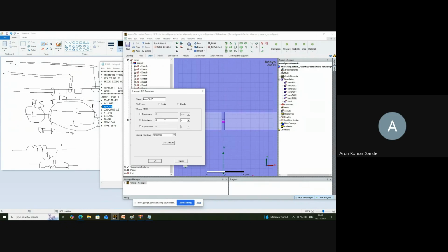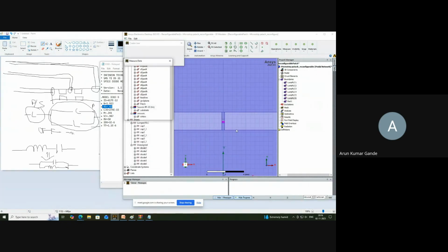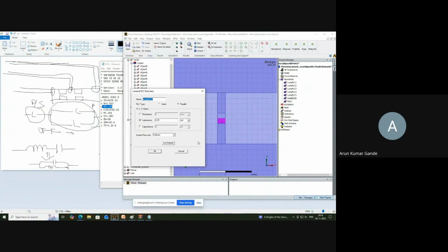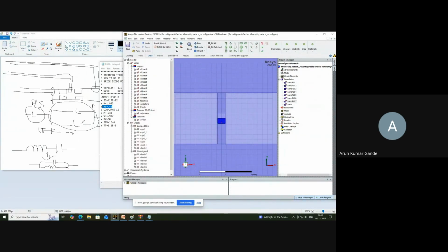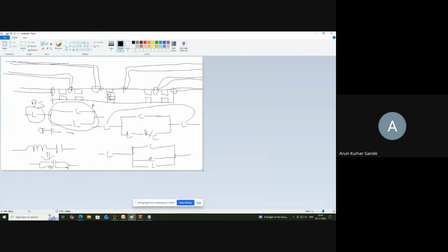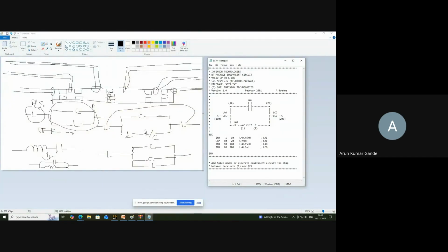So I'll define here 0.25 nanohenry, right? And then I'll define a line which goes from top to bottom. And then I have C and L. This C is my total capacitance CT. Basically, when I'm transforming this LC, this is CJ0, this is L, which according to this is 0.45 nanohenry, followed by my 0.06 picofarad. That I am converting to series LC. So there is a transformation here. Accordingly, my L and C values are going to change, right? And my parasitic capacitance, whatever I have here, is 90 femtofarads. So that 90 femtofarads I'll add to the converted capacitance, right?